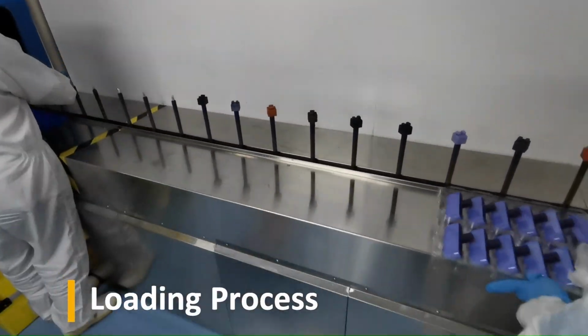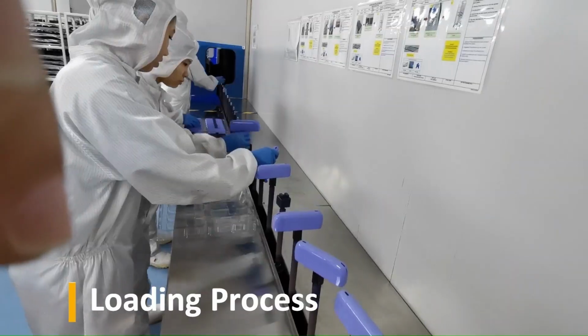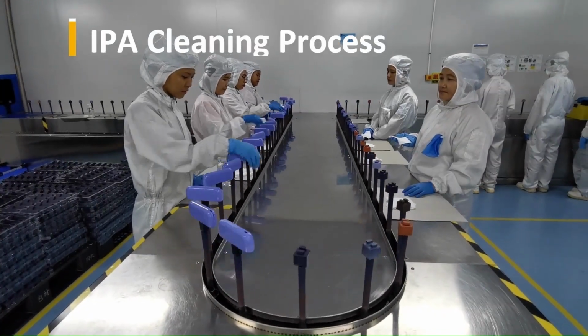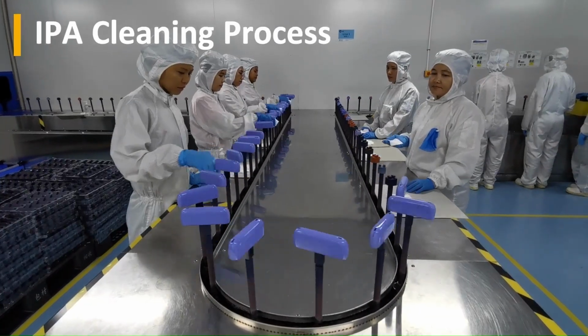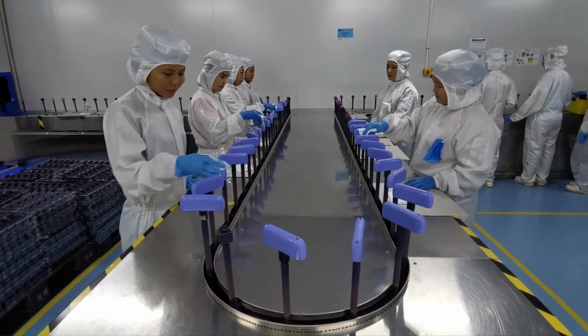Here, spindle cover is removed from top of the spindle, and product with installed jig is loaded into each spindle bar. Then, conveyor moves to next process for IPA cleaning. It is essential to remove oil, grease, and contaminants on the product surface.